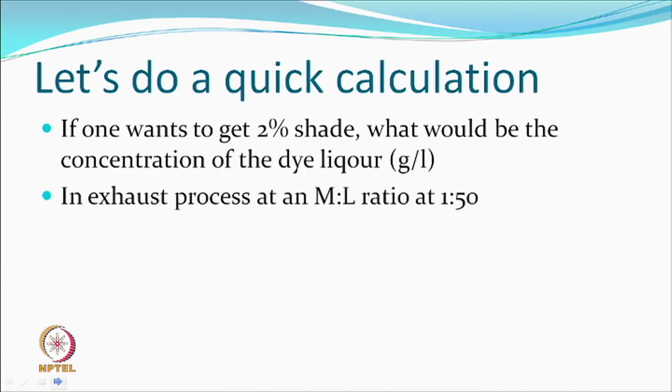So, in an exhaust process, okay. You understand what an exhaust process is? Everybody understands? An exhaust process is where you take the fiber and the liquor and keep working on it till you believe the dye has gone from the solution to the fiber. The bath has exhausted, and then you stop the dyeing and get out of it.